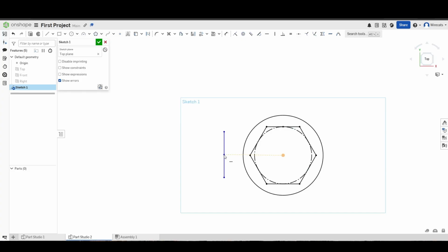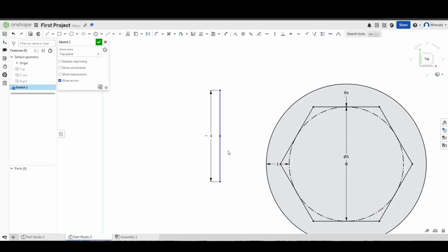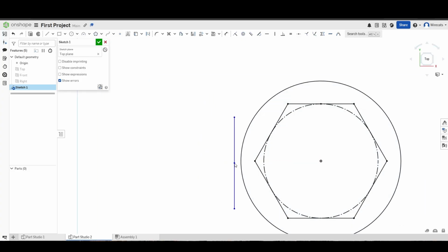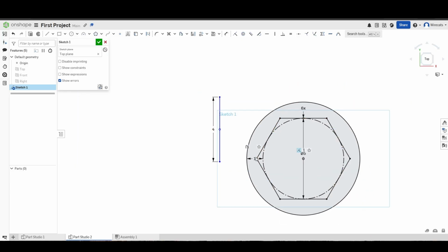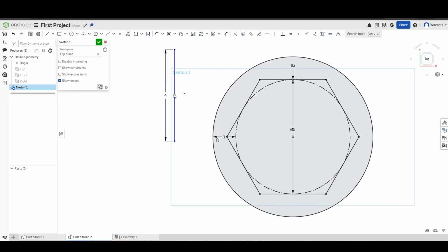And now what do we do with this? We want to make a whole handle out of it, right? If we put it just on the circle somewhere, it won't really make sense. We want it to be lined perfectly with the center of the handle. So I can use the yellow lines as a remembrance tool. If I hover over this point right here and then I drag away, Onshape remembers that yellow point I was hovering over, and it'll automatically make a horizontal constraint so that these two stay horizontal to one another.